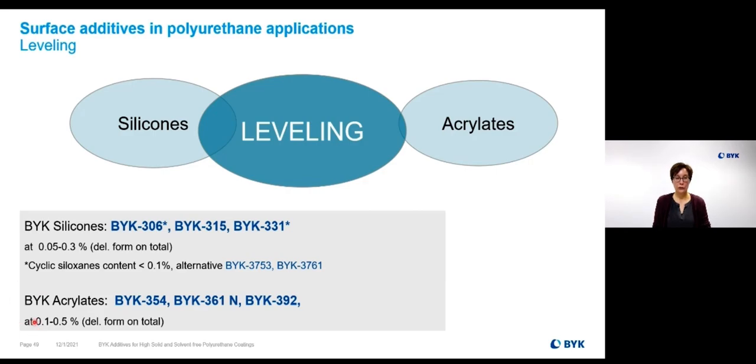It will not have any influence on the final appearance. And as mentioned, for the fine-tuning, we have our acrylates, like BYK 354, 361N, or BYK 392. Here, we recommend to start with 0.1 up to 0.5% delivery form on total.